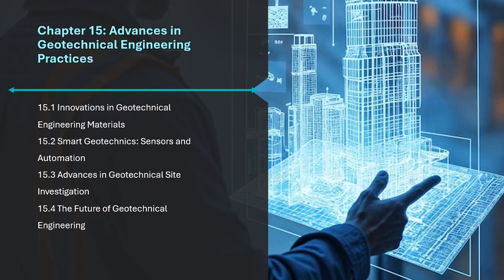Smart foundations and structures. Smart foundations. Foundations equipped with embedded sensors can provide valuable data on soil conditions, load distribution, and settlement in real time. These systems allow for continuous monitoring of foundation performance, ensuring that they are functioning within acceptable limits and helping engineers detect any issues early.